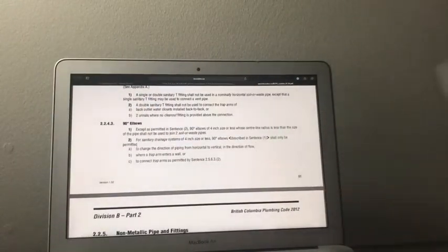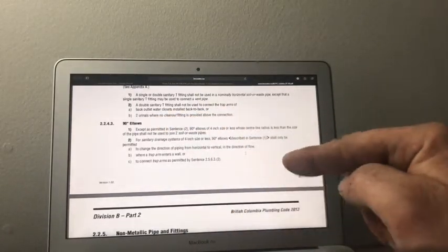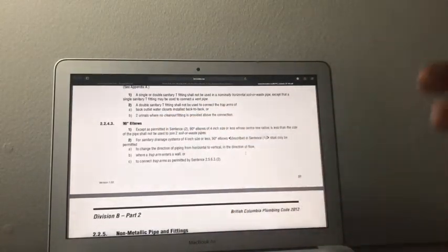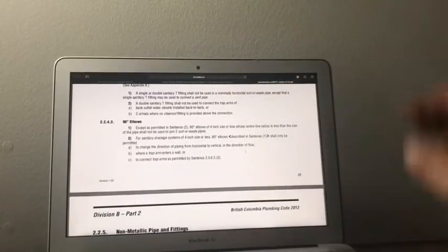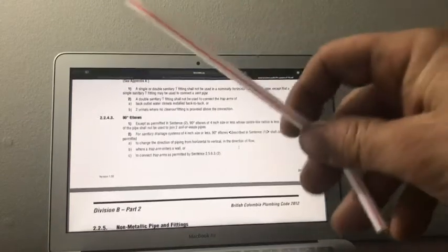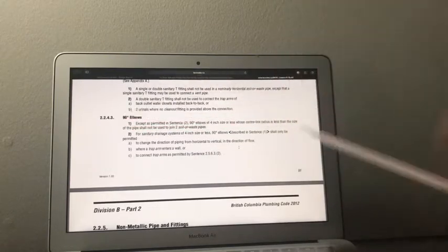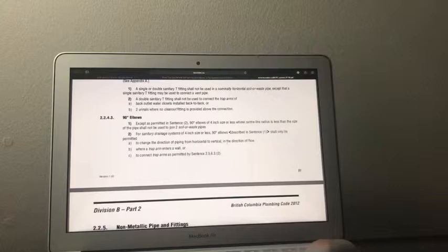In direction of flow, it also adds there. But for overthinkers, I wouldn't get too carried away thinking about direction of flow. I can't really think of a situation where you put a sanitary tee like that and the inspector would allow something like that to connect there. Even if you put a cleanout, it doesn't permit cleaning out of the entire system. So in my experience, I can only think of this situation for going horizontal to vertical, and that's the only direction of flow.